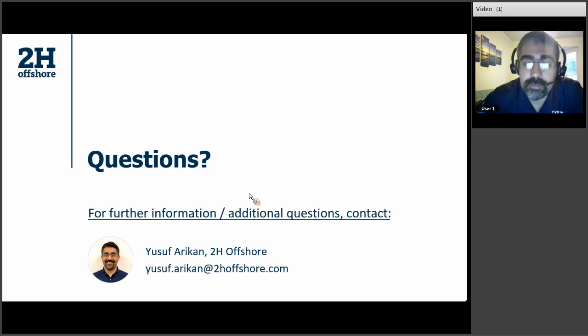Okay, great. I think we're going to squeeze in one more. Has the W power cable configuration been done before? The W power cable configuration is actually not a new idea. It is used in the oil and gas industry, where umbilicals between nearby vessels can be connected like that. So it is field tested. It is done before, so it's not new. All the components, the bend stiffener and the buoyancy modules, are field proven, field tested, qualified components, and yeah, it is a mature concept, let's say.